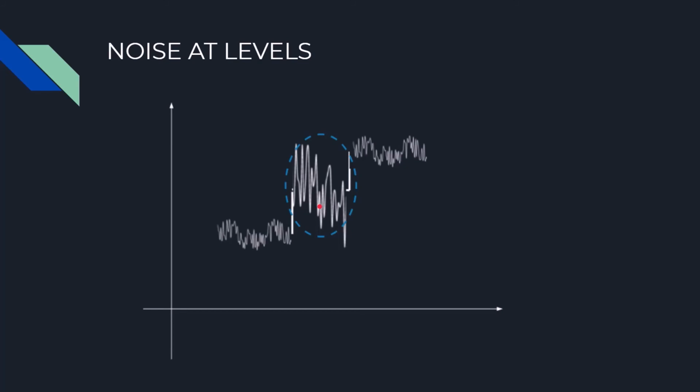Hence, selecting the optimal step size is always a trade-off, as lower step sizes might create interference of noise with levels and higher step sizes lead to more error between the actual and quantized signal. We have now completed all the three topics that we wanted to cover in this tutorial.